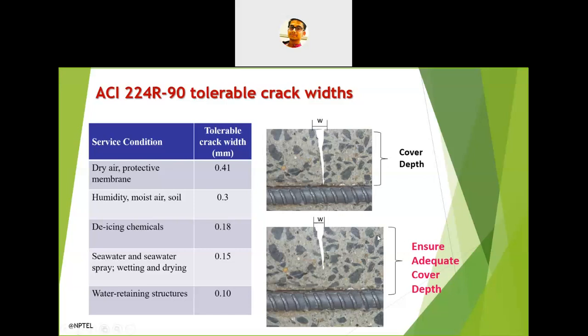Due to this adequate cover depth, the crack doesn't reach the steel surface. But if the cover depth is less, you may have some problem like this. So adoption of adequate cover depth is quite mandatory to reduce the ingress of cracks towards the steel surface.